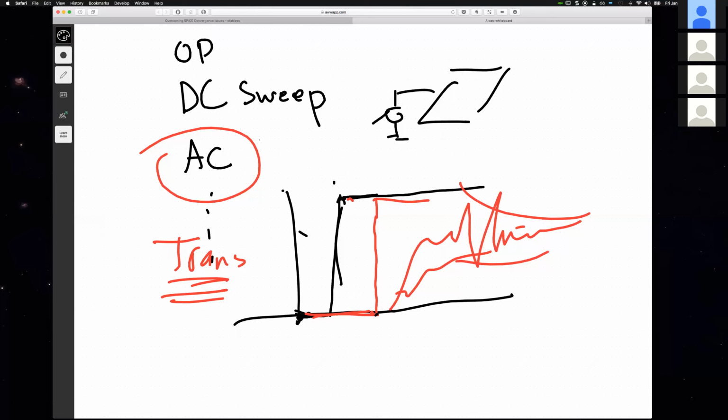Because the reality is, if you're putting that chip or the IP in a system, there are multiple voltages that wake up at different times, and the sequencing of these voltages is important to avoid leakage or power consumption due to unintended short circuit currents.